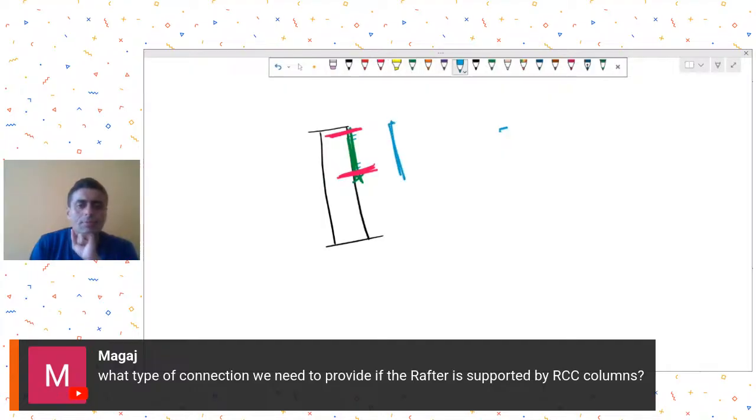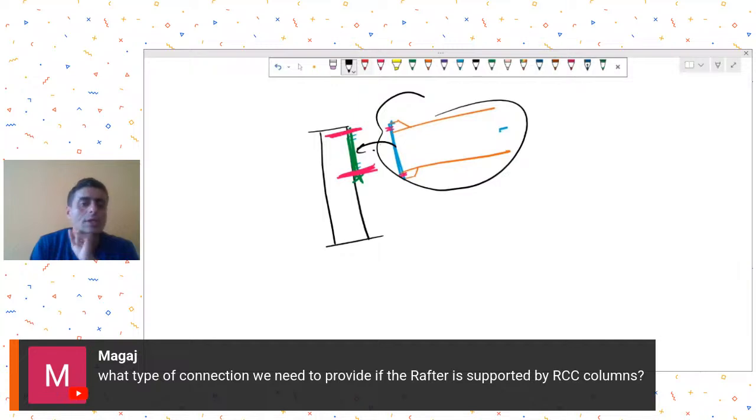This is my beam plate, and this is my beam with stiffeners and with matching holes for these anchors, and then you bring the system over here, do the on-site welding, and then do the bolting also. If you want to avoid on-site welding, maybe just the bolting over here. This can be one of the options.